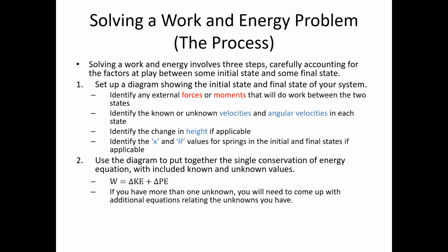Next, we're going to use the diagram to put together the single energy equation: W equals delta KE plus delta PE, or alternatively, our conservation of energy equation we just talked about. If we have more than one unknown in this equation, we need to come up with some additional equations, some kinematics or just geometry relationships, to relate those unknowns. And then finally, solve the equations for unknown quantities.